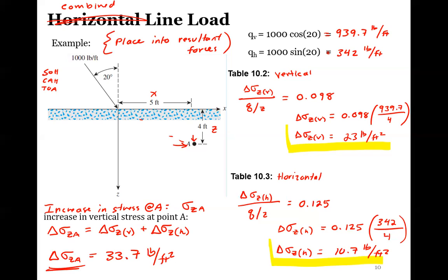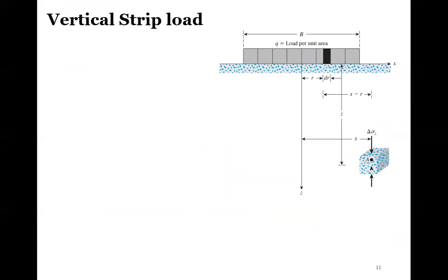So with all this math on point loads, luckily the same technique applies. As we were saying before, oftentimes point loads are okay to estimate, but when we're actually getting into the design of a structure, what we have is a load being distributed across a footprint, an area. So they took the same math and modeled a single point load as a bunch of point loads going left and right, an infinitesimal amount, and then we could create an equation for a vertical strip load.